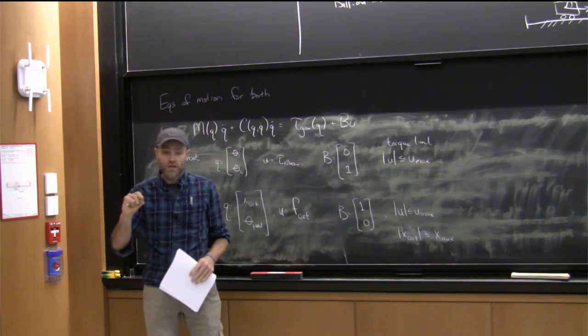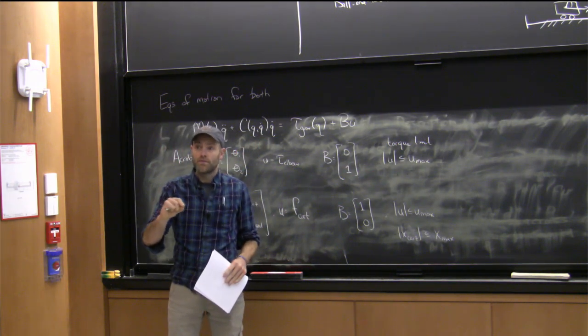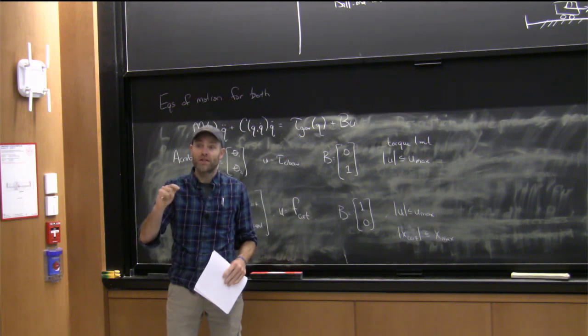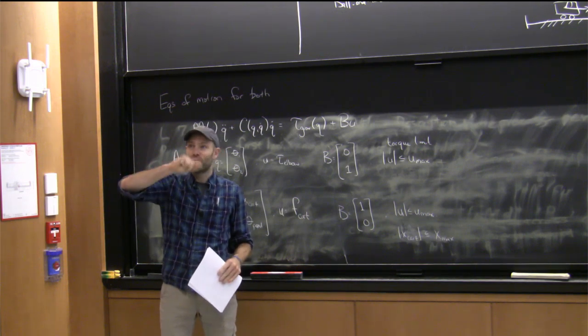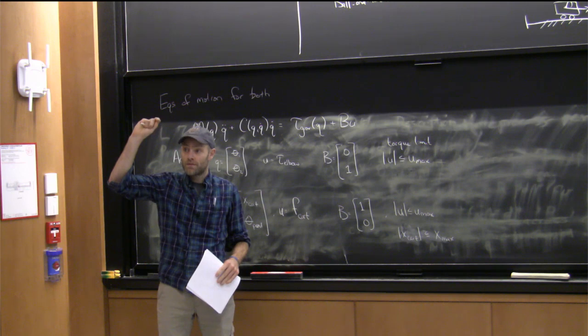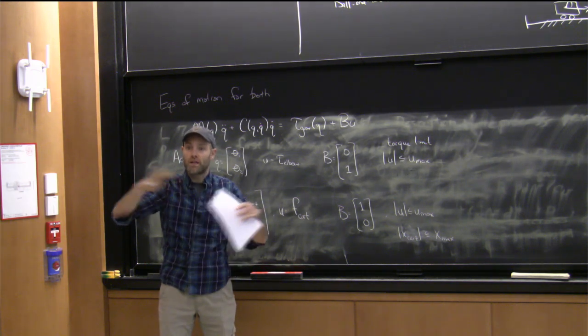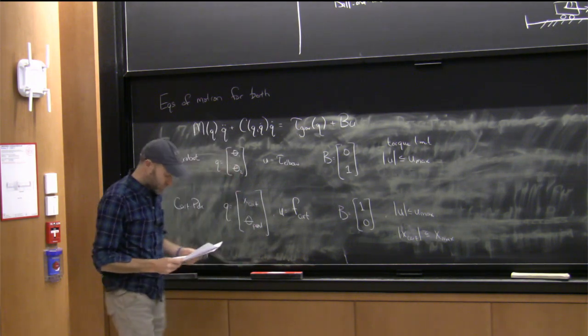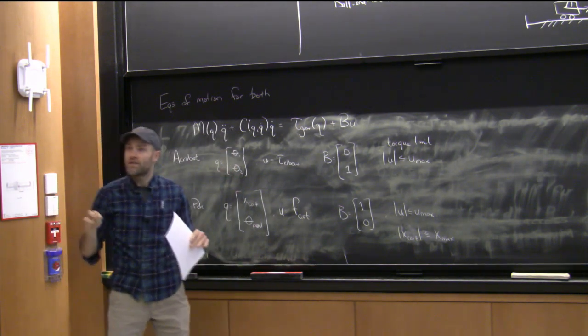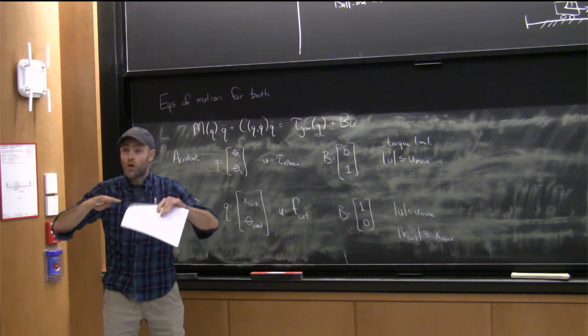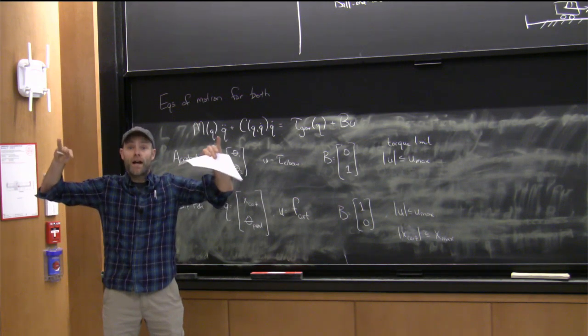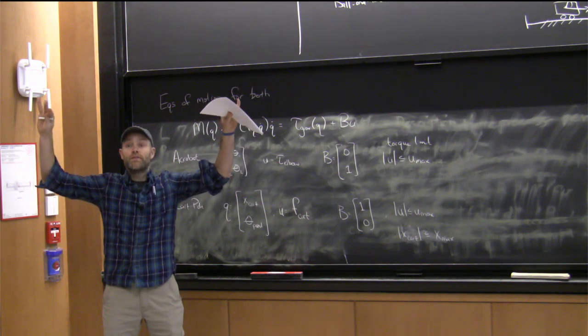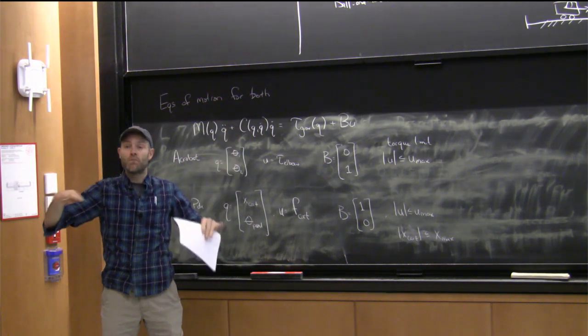So, especially as the torque limits go down, you will see value iteration fail for numerical reasons, suggesting that there is no solution that has finite cost, but really it's just because the resolution's not high enough. It's a numerical error. What would value iteration look like if it said that? The cost-to-go would just get higher and higher on every iteration. It would never converge.